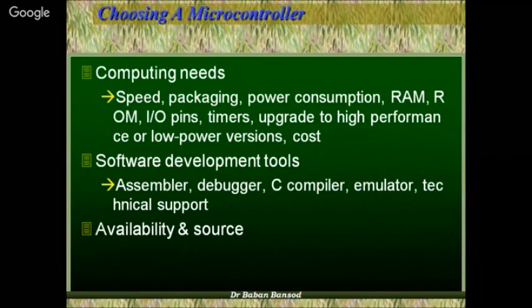As I was telling you, one of its features is a 21-bit program counter. So the addressability goes as high as 2 megabytes. In the 8051, we see only up to 64K, because the address lines are 16, and 2 to the power 16 is 64K.